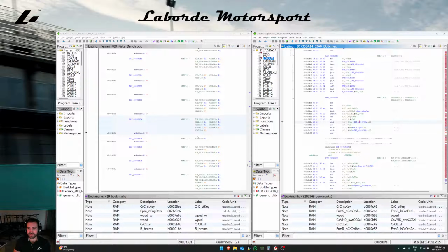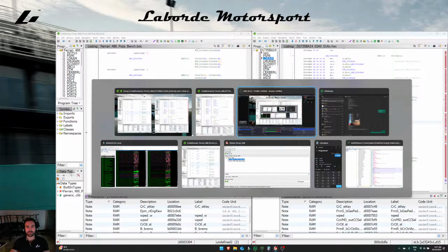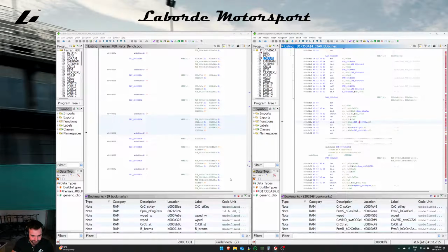So the first thing I'm trying to do here is come up with a possible list of engine speed variables that are sent over the CAN bus to the cluster, and the cluster obviously is the tacho in front of you, which is used to indicate the current vehicle speed, engine speed, temperatures and all those sorts of things. So what I'm trying to do is hook into the engine speed variable that goes on the CAN and indicate the current selected map. It's all going to be used for multi-mapping and map switching and all those sorts of things. Cool beans, so let's get straight into it.